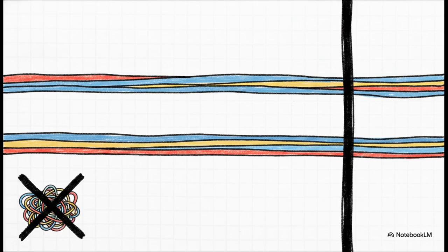Once you've got them classified, you create sub-bundles by function and physically separate them within the main harness. Keeping those parallel runs spaced as far apart as possible drastically reduces crosstalk. And hey, if lines absolutely must intersect, make sure they cross strictly at 90-degree angles. That minimizes the coupling area between the wires.